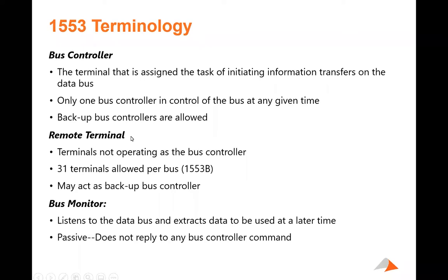That way, because sometimes an LRU can be up and operational, yet not be able to send a message, if you just have a discrete line, it could be holding the line up, but it in essence isn't working. Remote terminals. Go ahead.